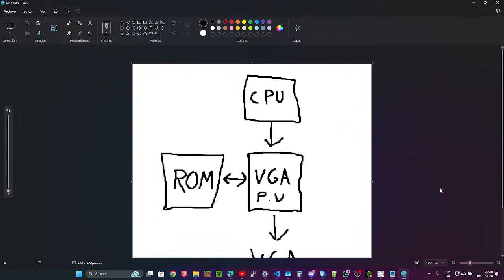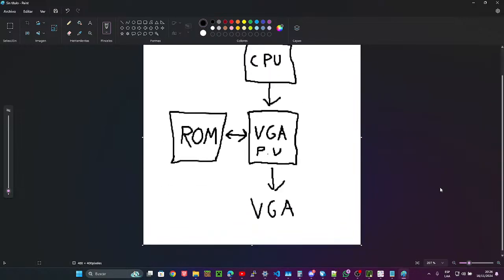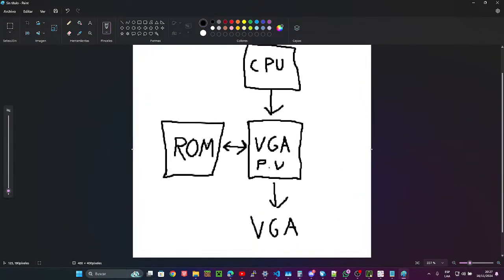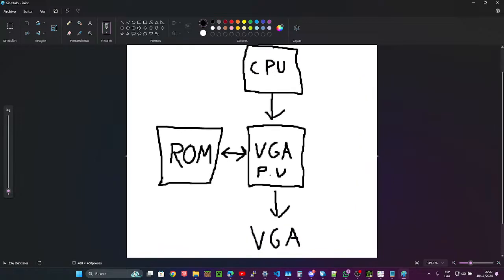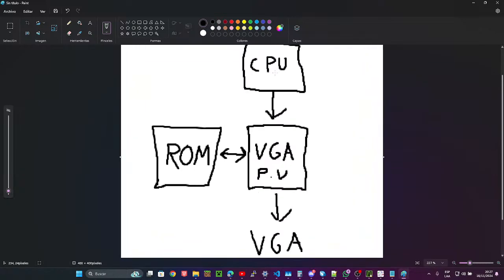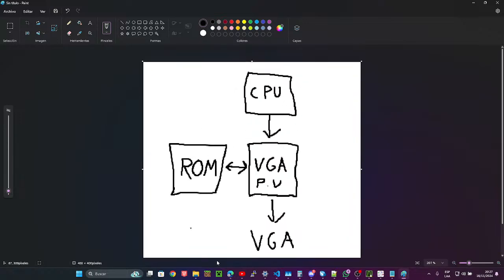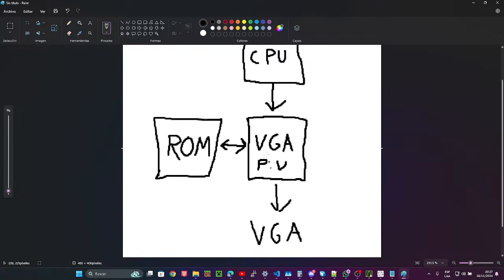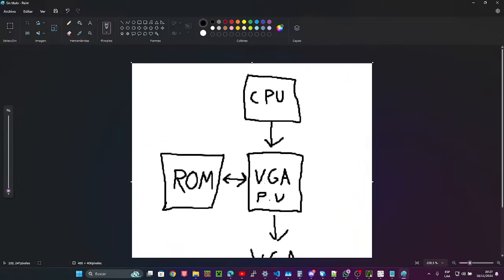Now you're talking about topology, because you have the CPU. You have to interface to the video memory somehow. One way is to have it go through the VGA circuit, and the other way is to have the memory shared. But if the memory is shared, that means you either have to share the bus, or you have to have two buses on the memory. Block RAMs have two buses, but don't rely on block RAMs. There are not that many on the Nano. I tried.